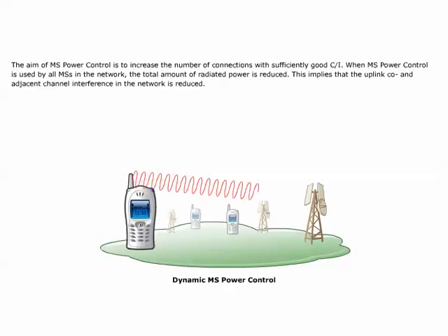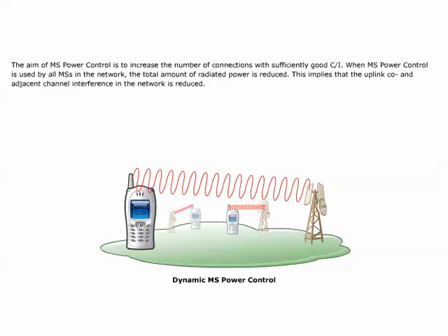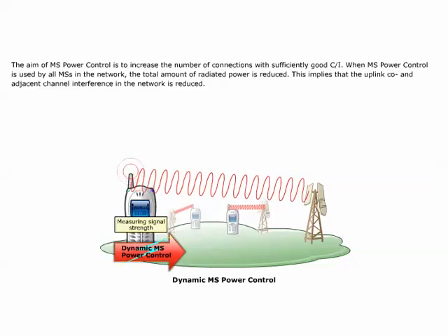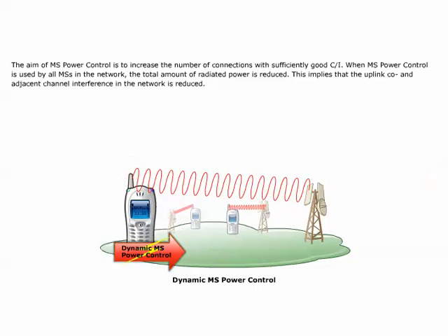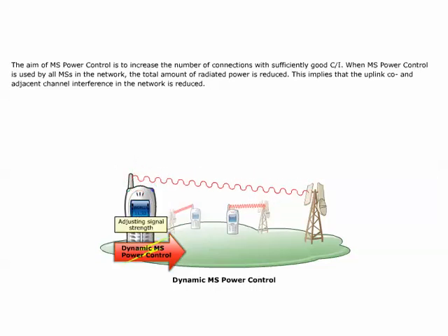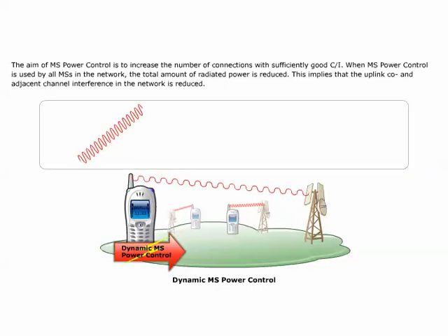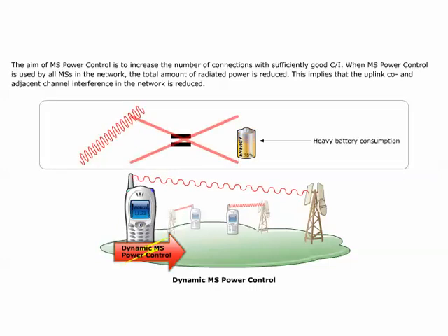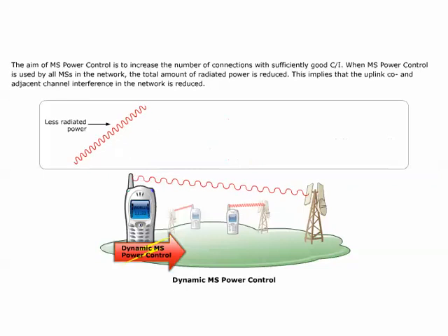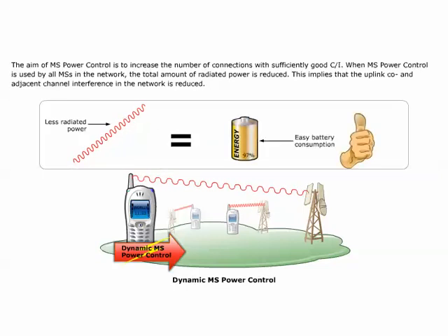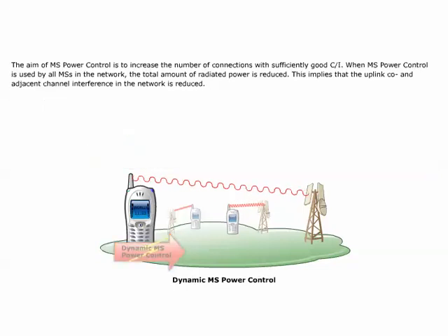The output power of a mobile station, MS, can be controlled during a connection. The controlling strategy is that a desired signal strength and quality shall be received in the base transceiver station, BTS. This user description describes the MS power control algorithm for circuit-switched connections only. The battery consumption is reduced in the MS, therefore recharging is needed less frequently, and the maximum possible speech time will increase when MS power control is used.